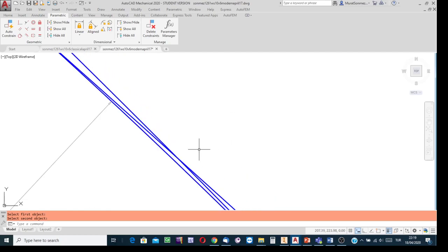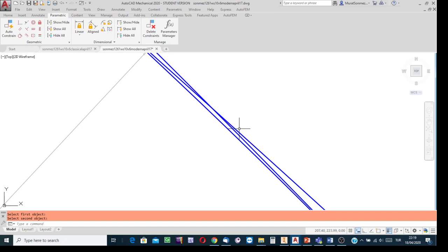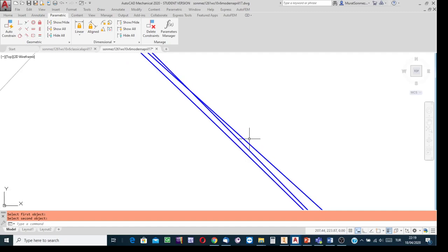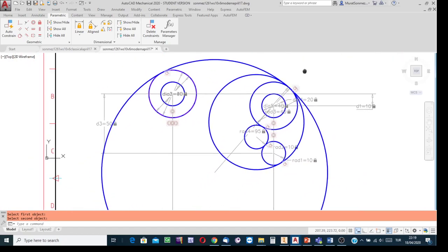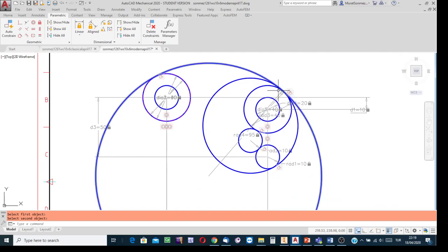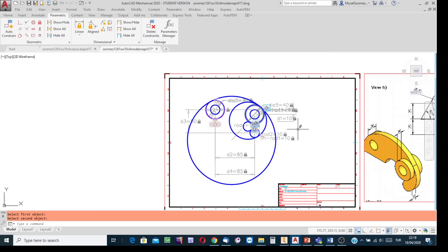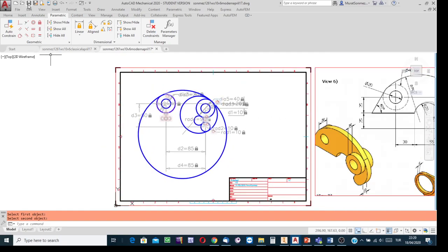When I zoom in, I see a few circle arcs. Which one is necessary, which one is unnecessary? You need to be more careful at the trimming stage because of the existence of such interference. Okay, save the file. Don't forget after each stage.